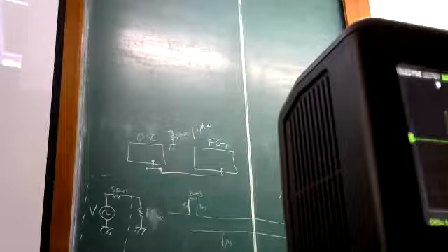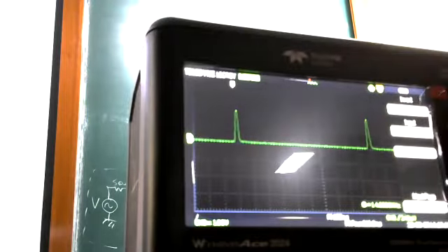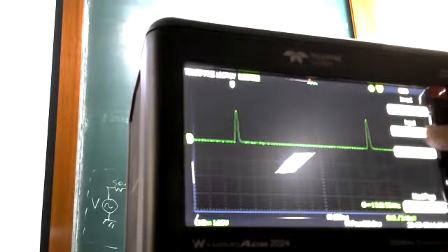So I'm going to put this back and show you. It's actually this setting here, which unfortunately is very difficult to see. It's this setting I'm changing, this one here. Currently it's set at 1 mega ohm. And if I put it to 50 ohms, you see it drops by a factor of 2. See, exactly 1 box. Okay.